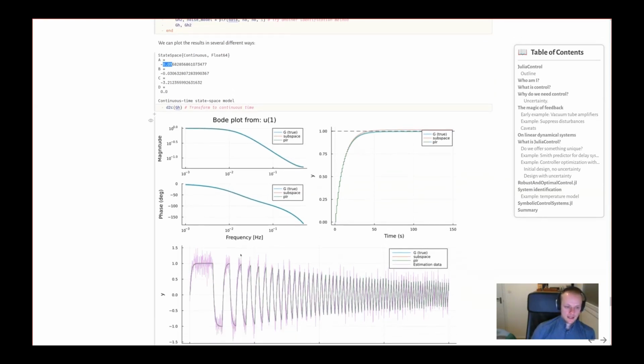So in practice, in real life, system identification is much more difficult because no systems are truly linear. You need to spend a lot of effort designing the input to the system when you do experiments. For some systems, in particular, if they are unstable, you must perform identification in closed loop. So if you want to identify a model of a quadcopter, you must actually have something that stabilizes the quadcopter, because if you don't have that, it will crash and then you get no data. But system identification becomes harder if you have closed loop.